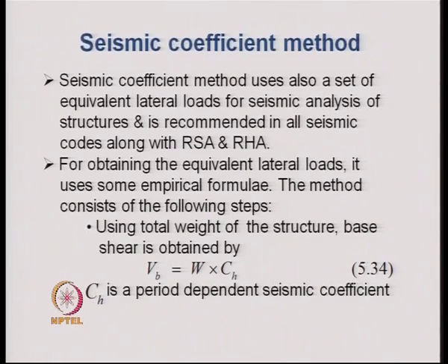The seismic coefficient method also prescribes a set of equivalent static lateral loads, and that equivalent static lateral load is applied onto the structure.